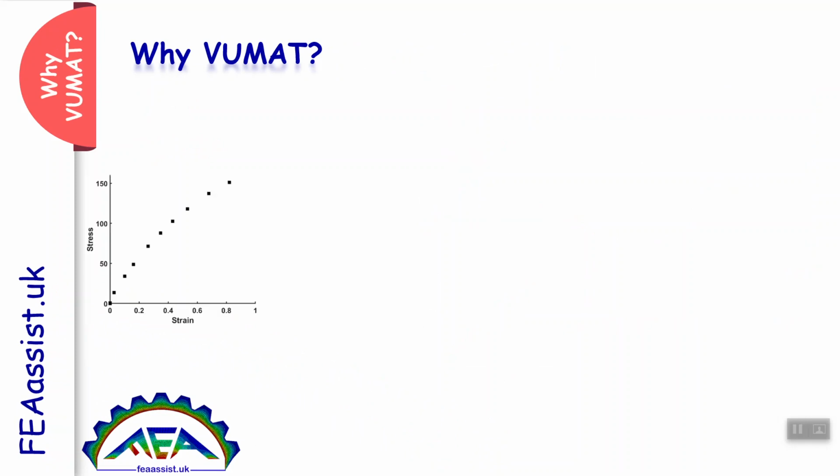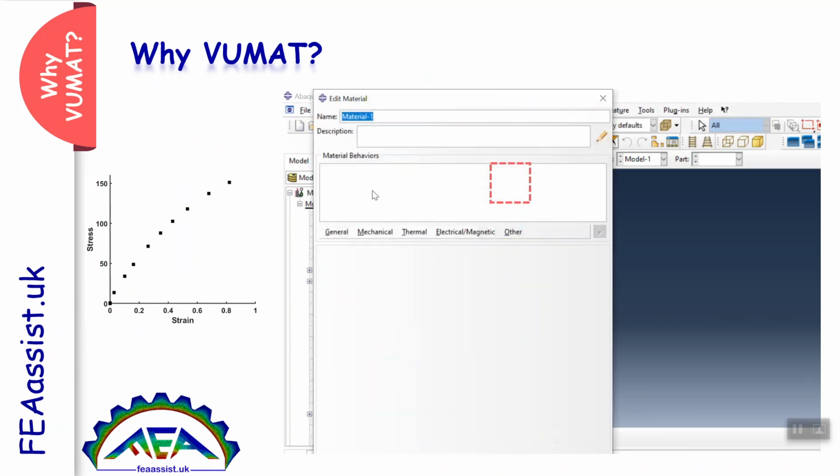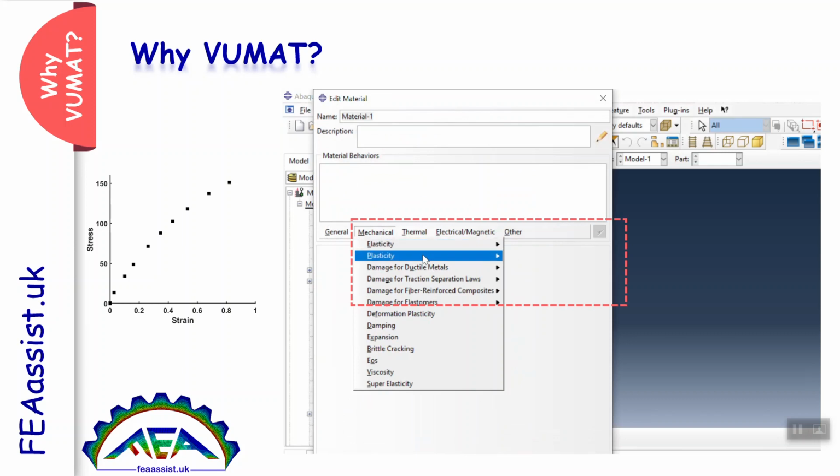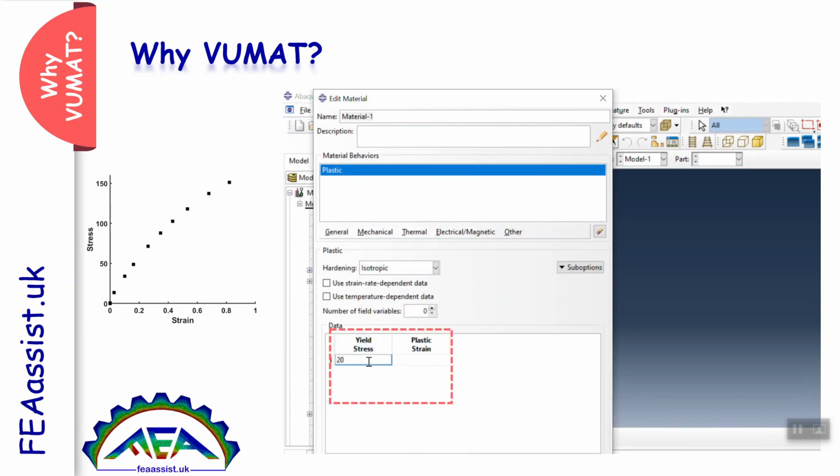The first strategy is that you have some of the points of your stress-strain or load displacement curve from the lab or published experimental results. Then you can easily go to the Abaqus property, define a new material, go to the plastic behavior and enter those points like this.